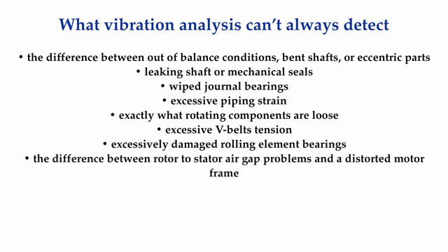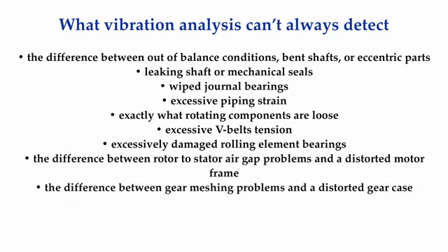Vibration analysis can often detect rotor to stator air gap problems, but it cannot differentiate between an air gap problem and a distorted motor case. The same is true for gears. Vibration analysis can detect gear mesh issues, but it cannot differentiate between a gear mesh problem and a distorted gear case.